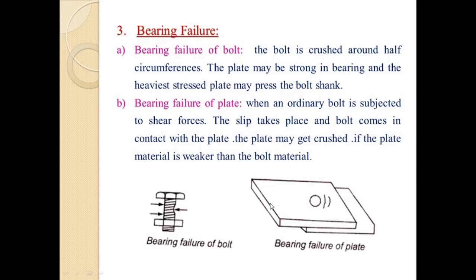Or if the plate material is not stronger than the bolt material, then bearing failure of plate happens. When an ordinary bolt is subjected to shear force, slip takes place and the bolt comes in contact with the plate. The plates may be crushed if the plate material is weaker than the bolt material.